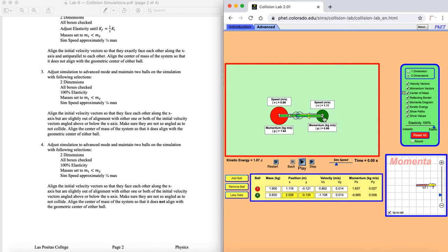No, you can get close enough. 24 and 23, yeah. So this is acceptable. When it's giving you trouble like that and it won't line up, that will happen occasionally. Just get within that last decimal point and make sure it's no more than a 0.005 difference. Okay, that's totally acceptable for this one. But a lot of times you will be able to get them to line up.